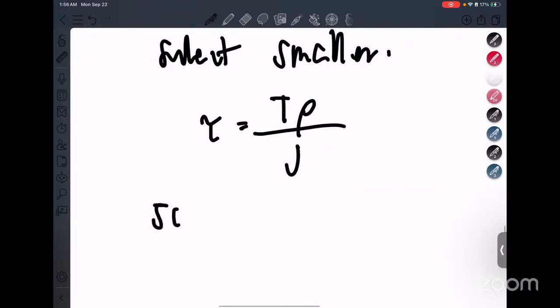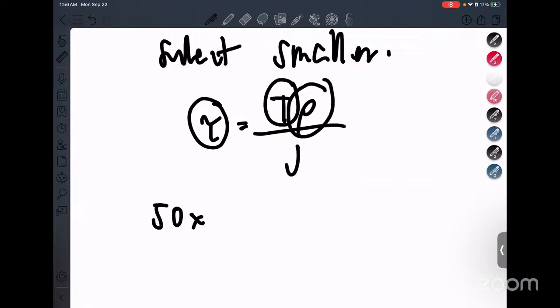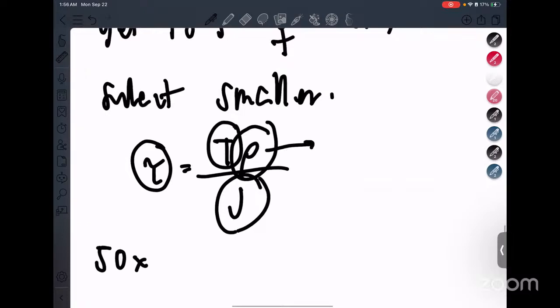So getting this will give us the shear stress given torsion given the rho, which is our radius, right? Our radius within the shaft over J. Again, special case if we're looking for the maximum, rho just becomes C, which is the actual radius of the shaft. Since we're getting maximum, we'll just use the maximum radius.